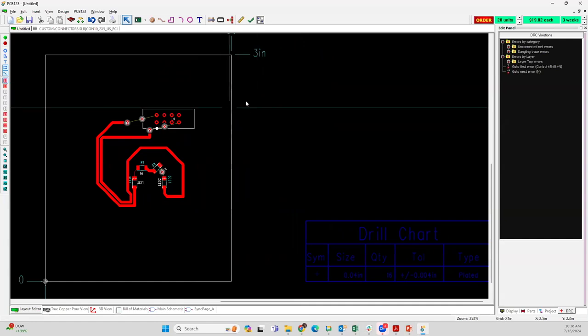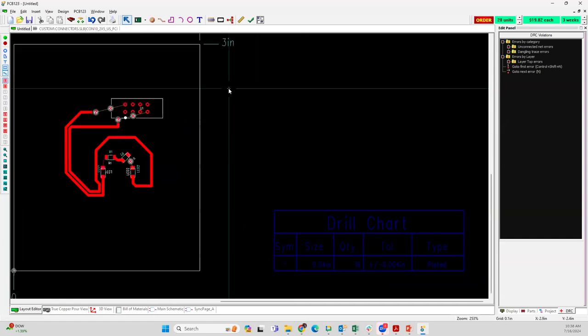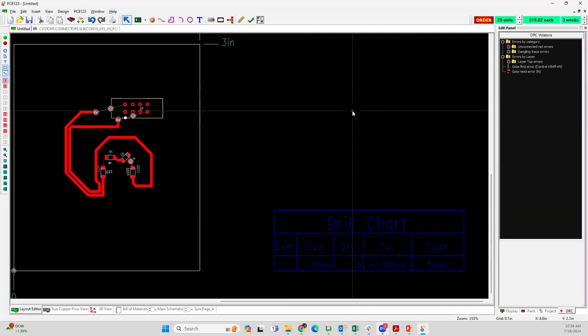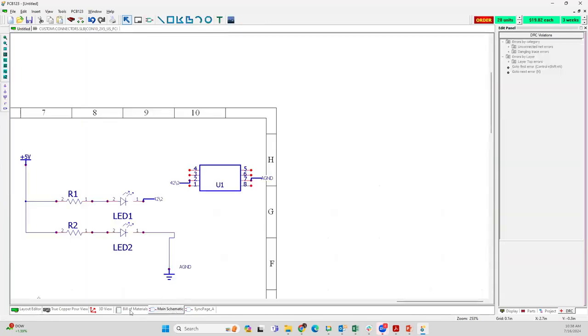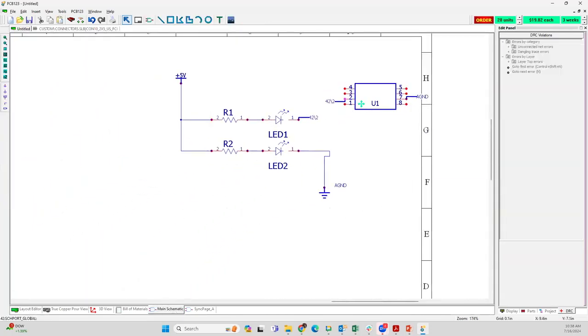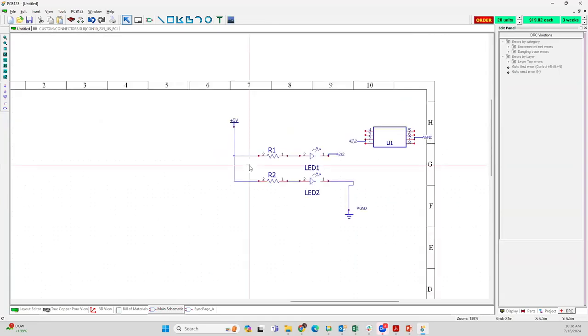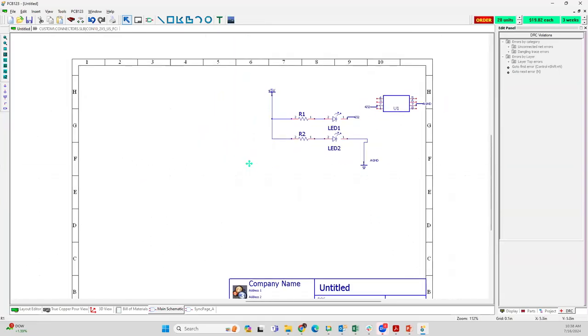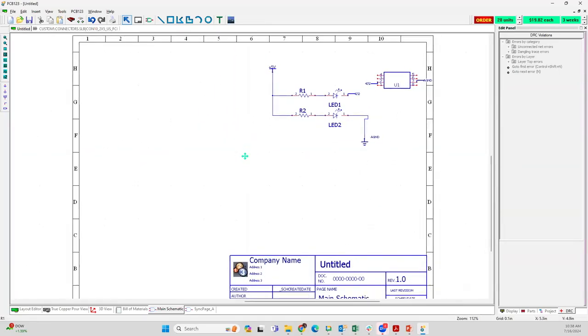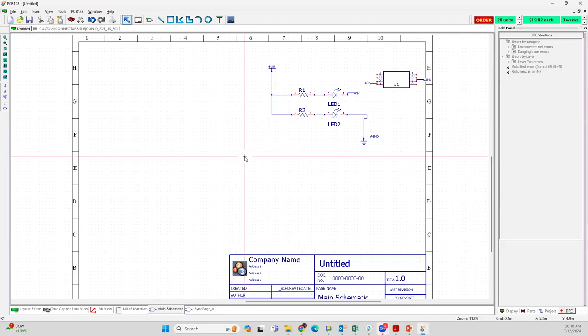That's weird. There's another question on importing schematics if you want to field that. Well, I created the schematic right here in the schematic tool in PCB123, and that's how I would recommend you do this. It's easy enough to do. It keeps your parts tied together and keeps your schematic and your board and your bill of materials all synchronized and handy. And you can go back and edit it quickly and easily.